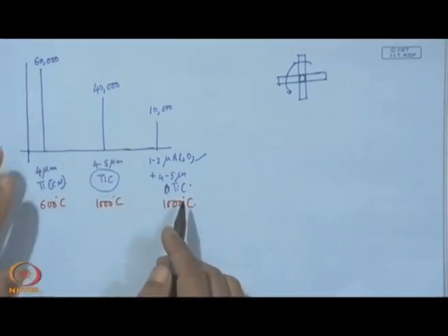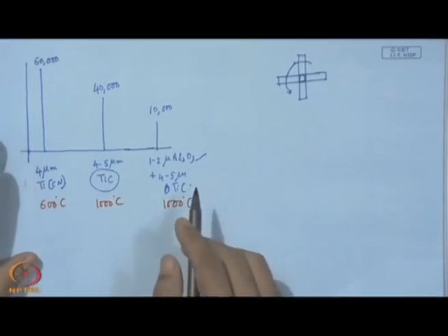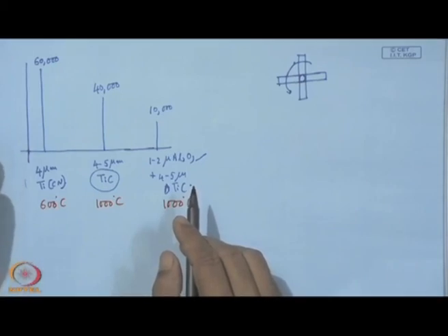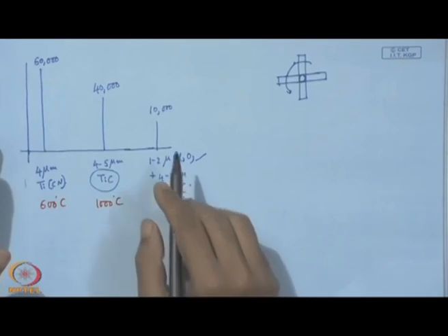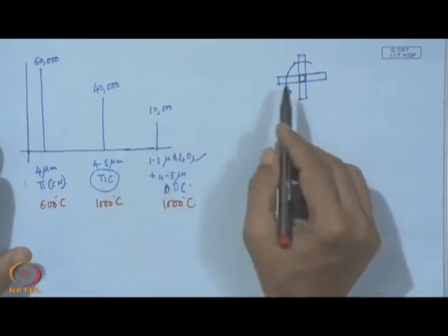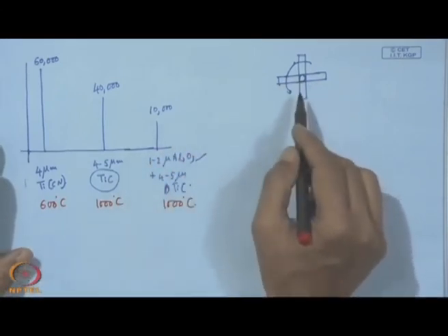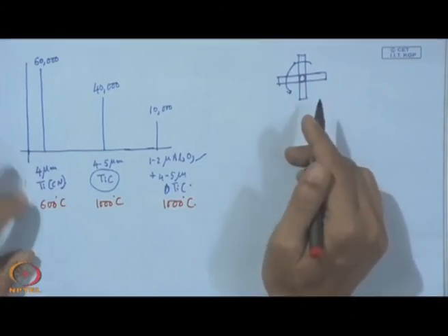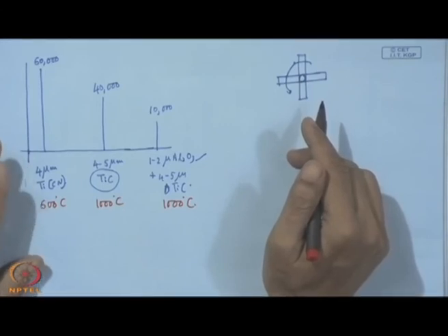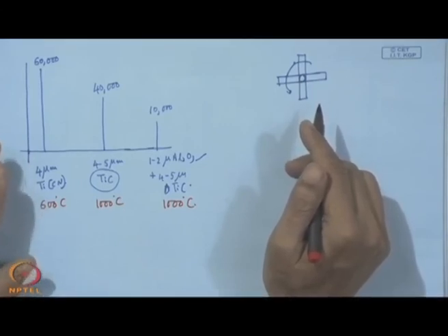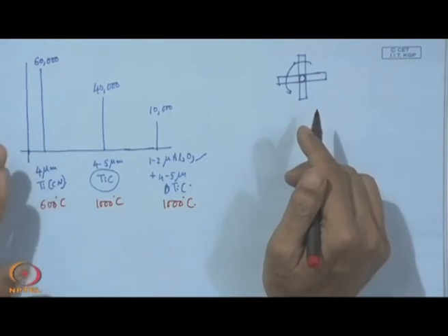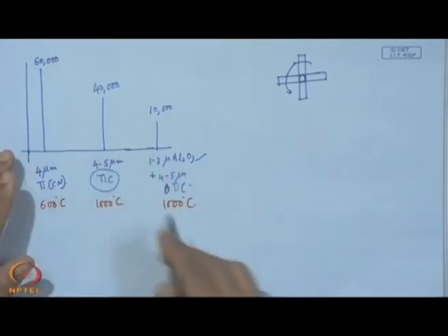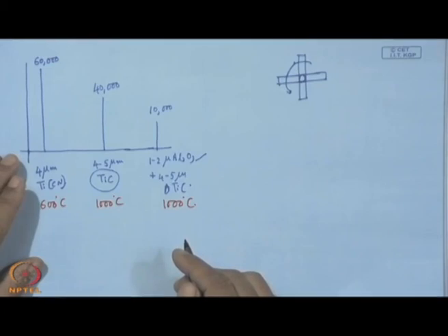It shows its strength in a machining environment where the material has some non-symmetry in its geometry, and while rotating it can give some kind of interruption in cut, and the coating with the cutting edge can survive more impacts compared to the conventional high temperature coating.